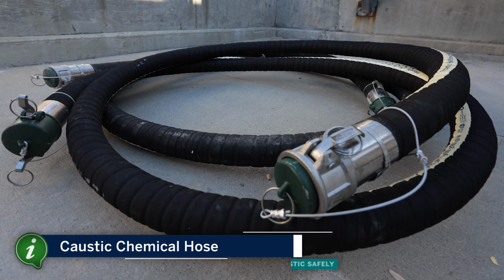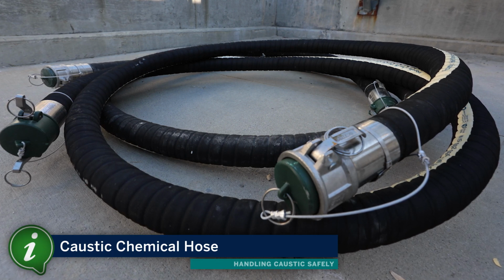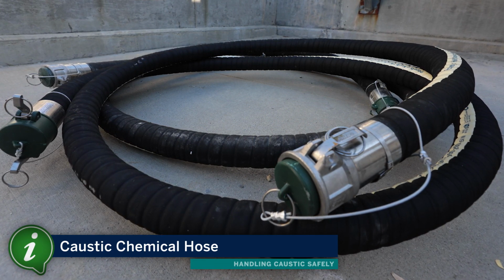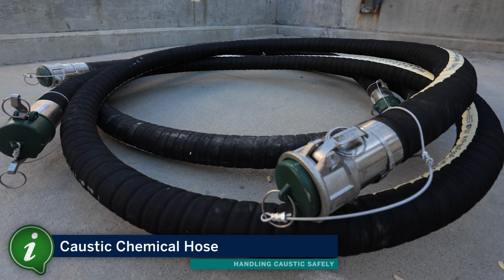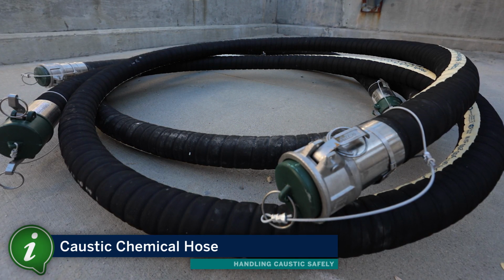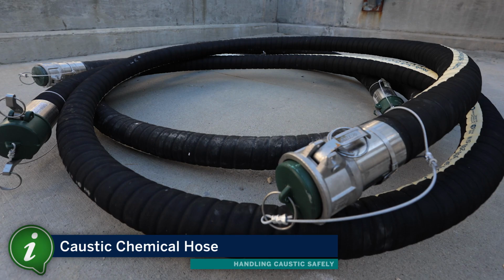Only chemical hoses designed specifically for caustic should be used for loading and unloading. Consult your chemical hose manufacturer for proper hose selection. Never use hoses with aluminum fittings.